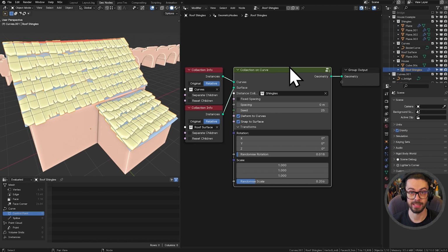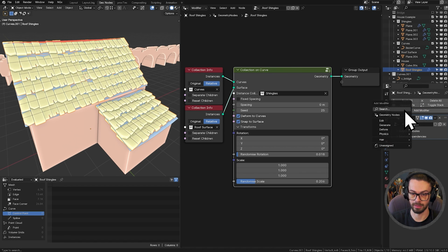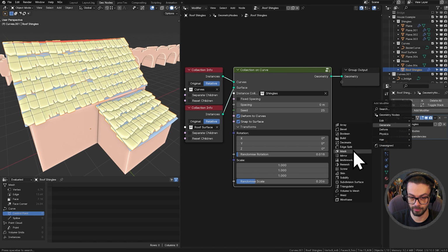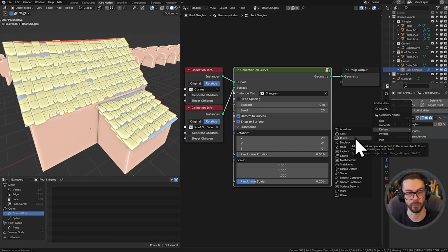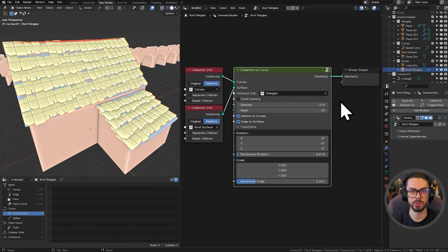The issue with that, obviously, is if we're building tools from scratch in geometry nodes, that means we're building very low-level tools. So, for example, in the last lecture, we built a curve deform node group, and that is essentially repeating the modifier behavior for the curve modifier, right? With a little bit of extra quality of life stuff because it's geometry nodes, but essentially we're building a very low-level tool there. You can use it for everything. If you wanted the use case, bending stuff, right? So it's way too general for a lot of people to really apply.